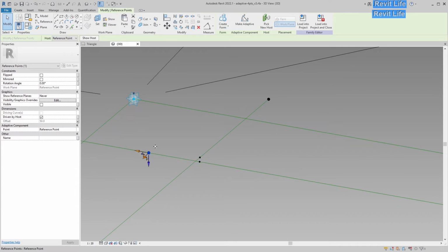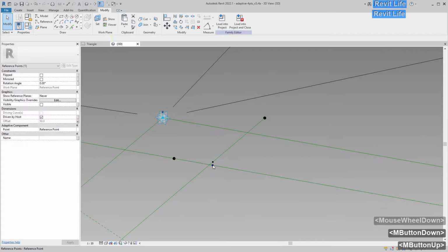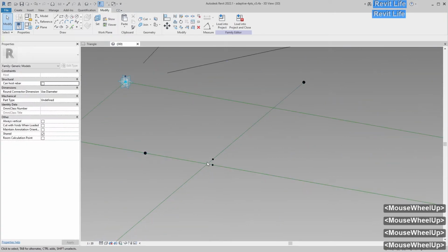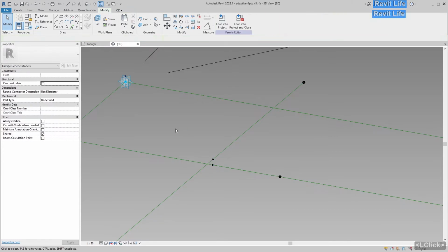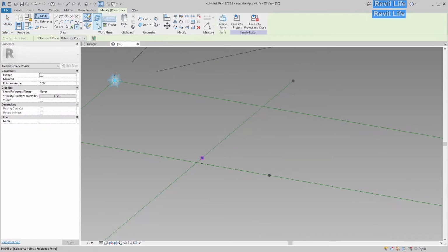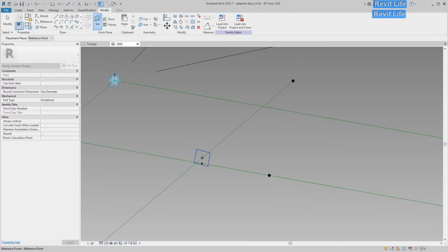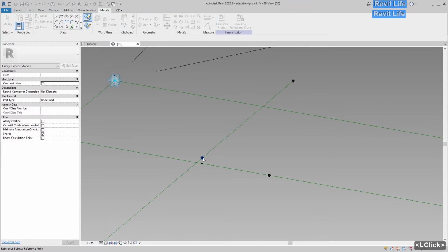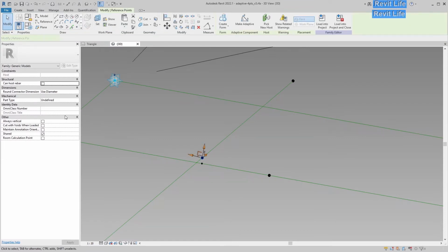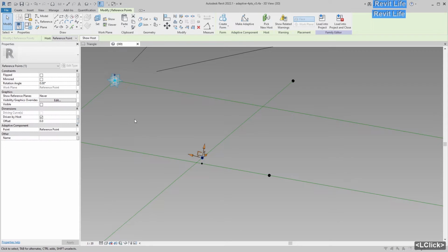And now if it moves on the wrong direction, select the host point and check flipped constraint. Now select point, set work plane, select work plane on the point, add point, select the added point, and add fillet parameter to the offset property.